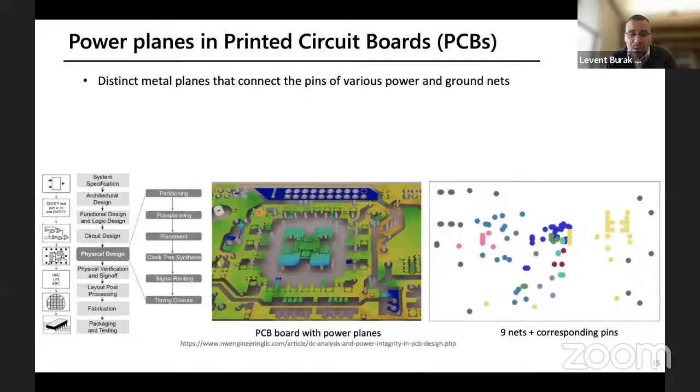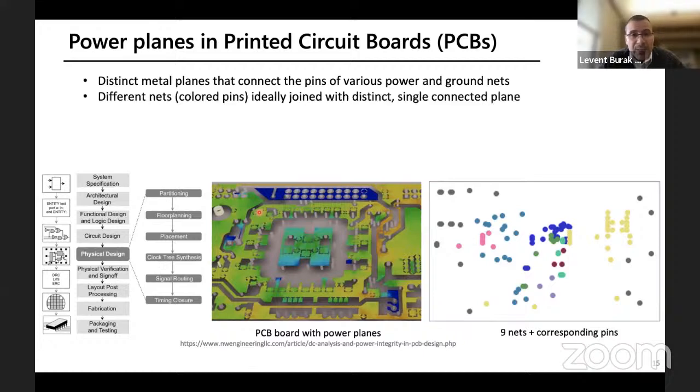And on a given circuit board, there could be multiple levels of power, meaning that you're not looking at just two planes of 5 volts versus 0 volts. You have multiple layers of these power levels. So you need to actually construct multiple different planes.